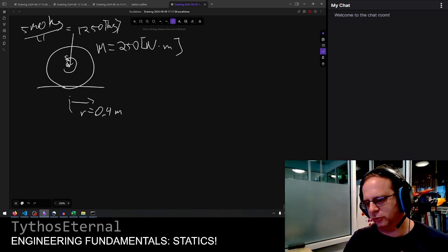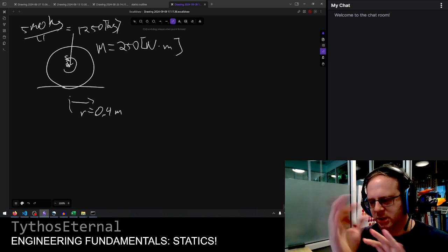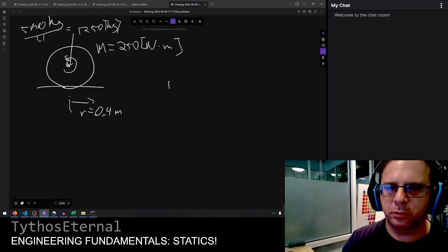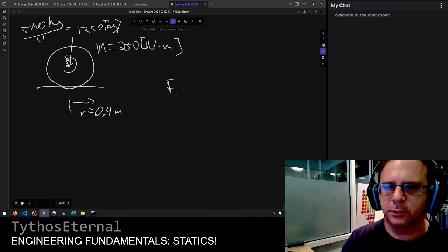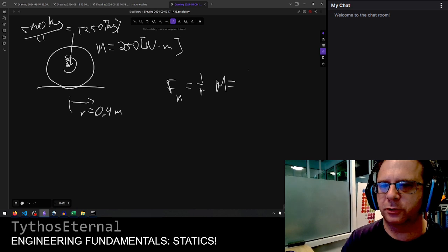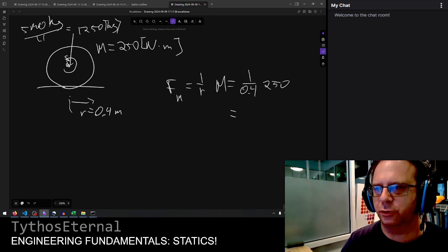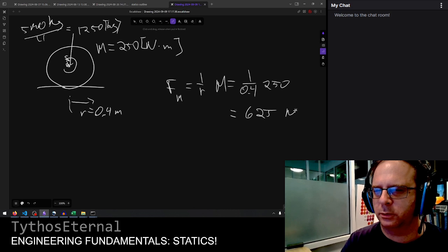So recall the slip condition is where that modeling of the frictional force is equal to the force being applied. So we know the force from the moment, this is just inverting the moment equation, right, is going to be something like this. So this is what the powertrain is applying to the surface. Newtons.